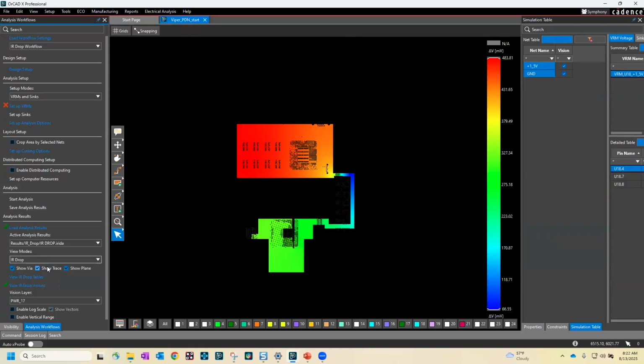So it gives you a lot of good visuals to allow you to see what's going on with the power in your design. And like every other aspect, from here you could go into the shape utilities and start making these shapes bigger. You could add more copper planes. You could add more vias. You could start moving parts around, but typically the result is going to be to add more copper or more conductor somewhere in the design.